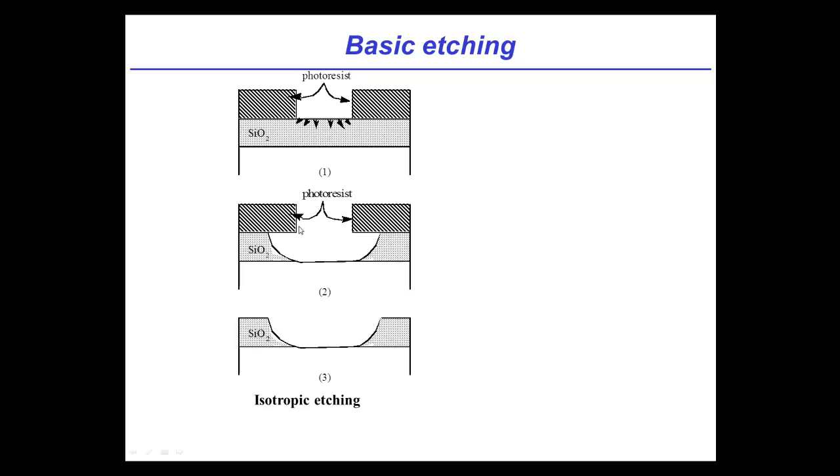And then if you get rid of the photoresist or whatever you might have used as your mask, we use photoresist because it's an easy example, you'd be left with something like this, which is an etched region. Now notice, HF doesn't etch silicon, so as soon as it hits the silicon, it stops. It can't do anything there, so it flattens out.